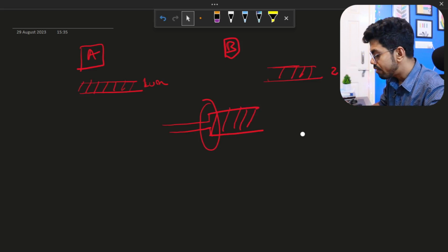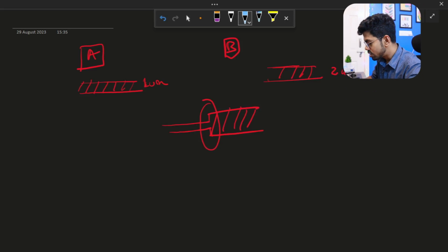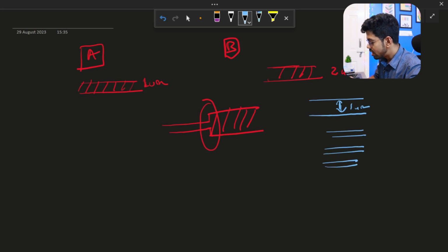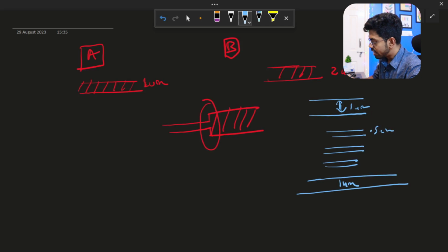Roughly, in practical design we decide that our power routing would be of some width like 1 micrometer, then we'll have some tracks for signal routing like 3 tracks, then another power route of 1 micrometer, and signal probably of 5 micrometer, and in between these two power lines a separation of maybe 10 micrometer.